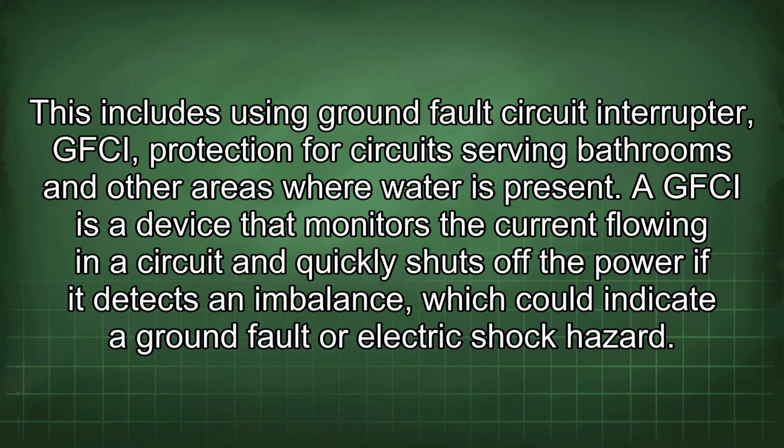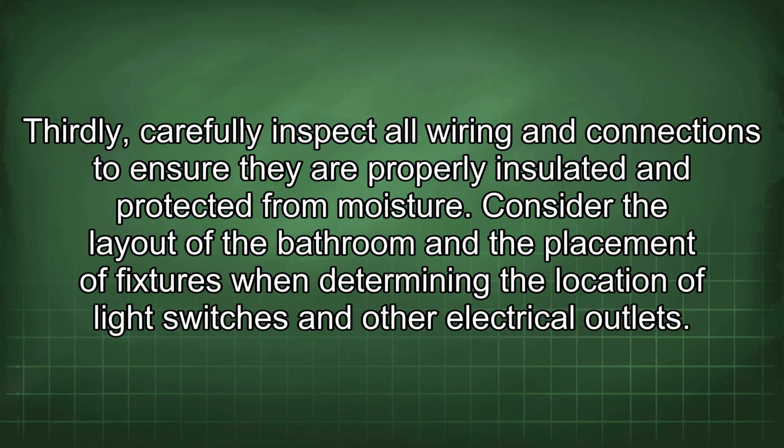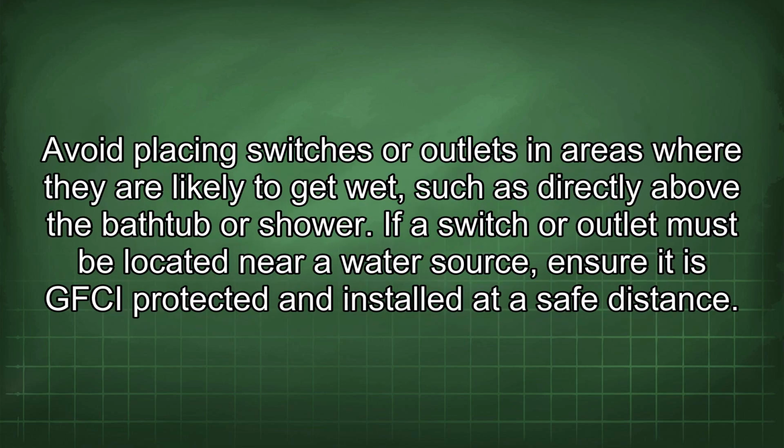A GFCI is a device that monitors the current flowing in a circuit and quickly shuts off the power if it detects an imbalance, which could indicate a ground fault or electric shock hazard. Thirdly, carefully inspect all wiring and connections to ensure they are properly insulated and protected from moisture. Consider the layout of the bathroom and the placement of fixtures when determining the location of light switches and other electrical outlets. Avoid placing switches or outlets in areas where they are likely to get wet, such as directly above the bathtub or shower. If a switch or outlet must be located near a water source, ensure it is GFCI protected and installed at a safe distance.